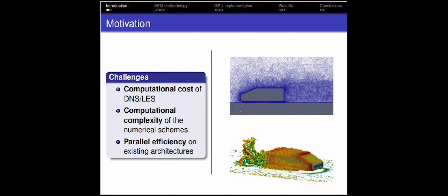The mesh being shown here in particular is actually a linearized version of the meshes that we use. So there are actually quite fewer elements, but wherever lines cross, there is actually a node. So meshes with a few 100,000 elements end up with quite a few million degrees of freedom. That's the direction that we're trying to move in.